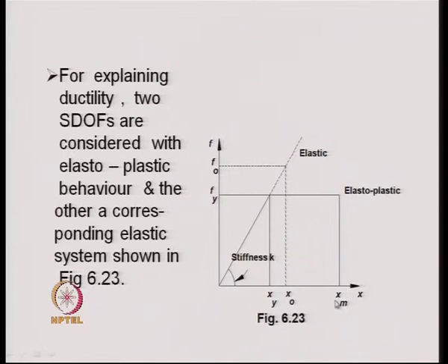Say xm is the maximum displacement that can take place in the single degree freedom system. xy is the yield displacement that is well defined with the help of the yield force and the stiffness of the system, and x0 is the displacement for a force of level F0 applied to the single degree freedom system, and it is assumed that the system is behaving as an elastic system.